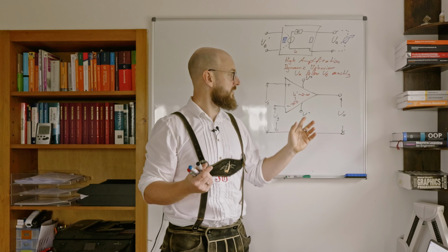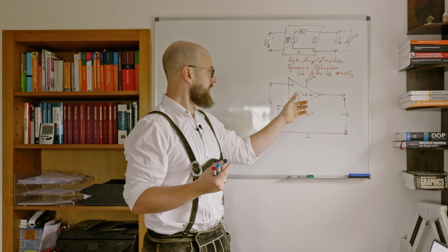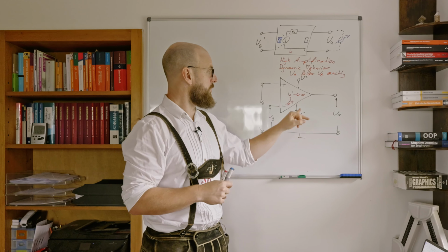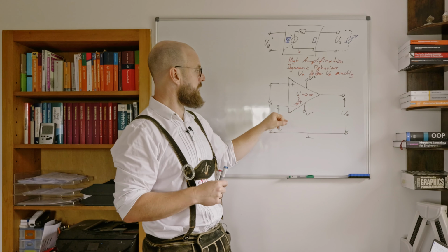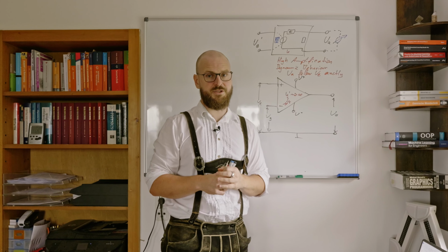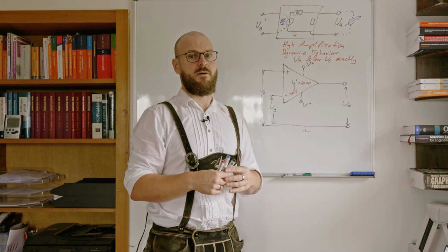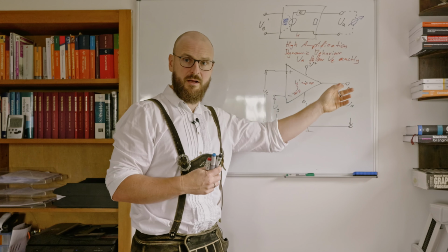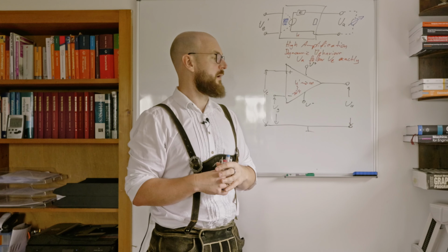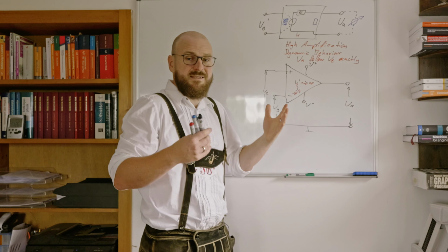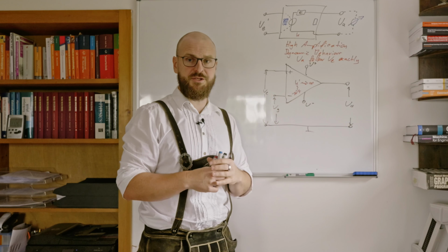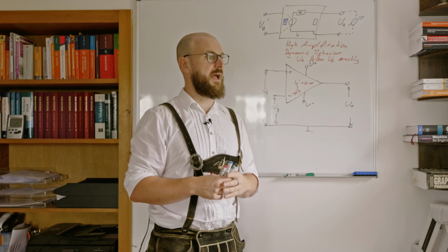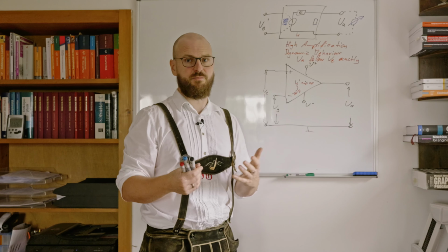But why is it that those amplification factors are chosen to be so large? It's easily said. By recoupling the output to the input, we can adjust the amplification by the amount of recoupling to the input of the operational amplifier. So, as long as we can reduce that amplification factor by rewiring, by recoupling, it is sensible somehow to give those operational amplifiers very large amplifications, meaning as large of an amplification as possible at all.